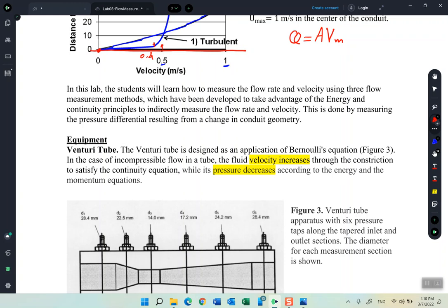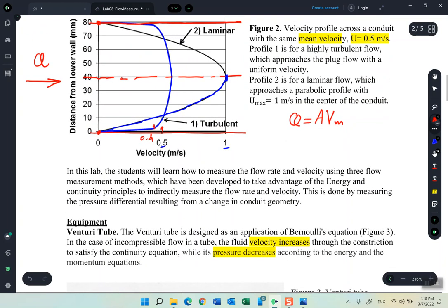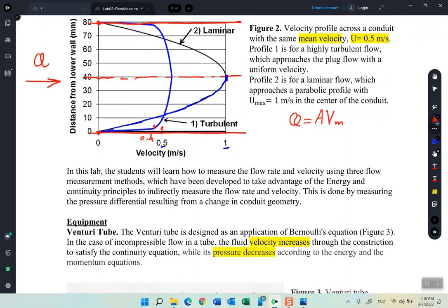No, you don't need to do that. We do that before giving you the velocity, but after getting the mean velocity, you can just plug it into the continuity equation to get the discharge. We don't need to do any calculations or equation manipulation to convert from the velocity of the parabolic shape to the mean velocity.